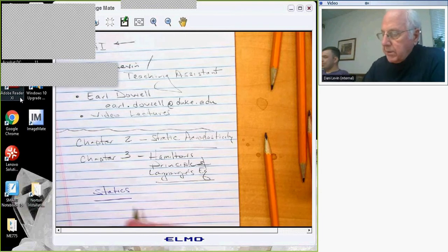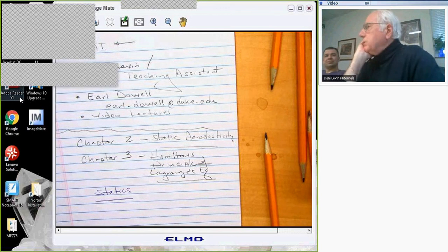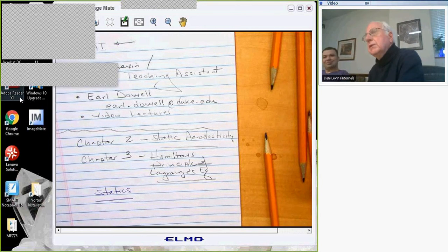And in either statics or dynamics, in an aeroelastic system, we're basically interested in two different kinds of situations. One is, is the system stable or not? If it's not stable, that means some large and potentially dangerous deformations of the structure may take place because of its interaction with the fluid. And we want to know about that. The other possibility is the system is stable, and we hope that that's true before the airplane finally flies, but it still may be deforming or possibly moving if it's dynamic, and we want to know how much. Because even if it's stable, if motion is too large, stresses are too large, whatever, we still are concerned about that.